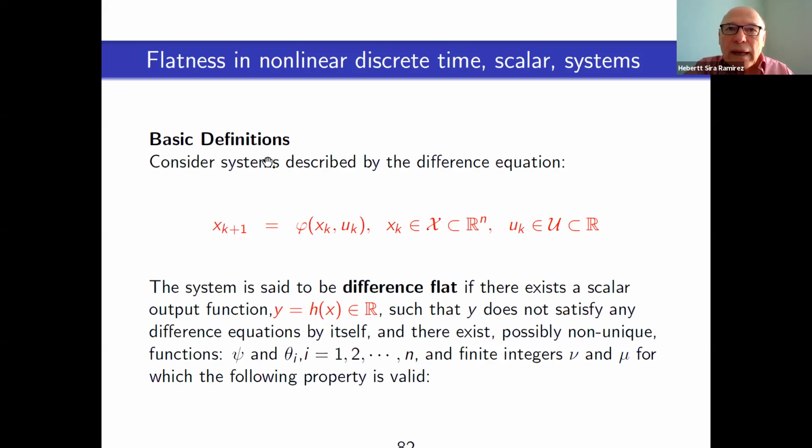And that will constrain our nonlinear systems to the class of static feedback linearizable systems. So you take u as a parameter in that function? No, u is the control input variable, it is one-dimensional, and for the time being, it doesn't affect the choice of the flat output. The flat output is only a function of state.